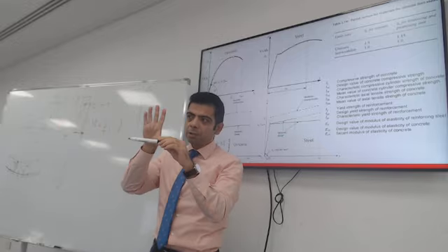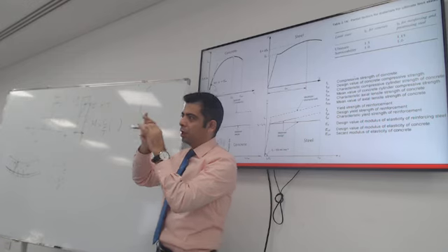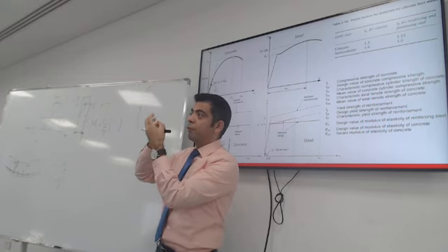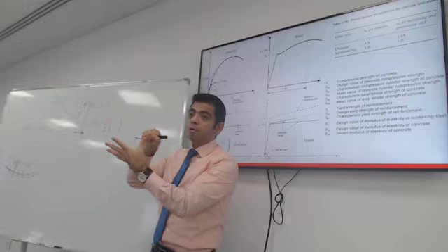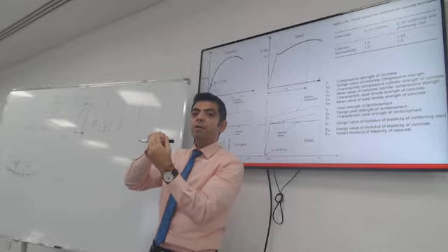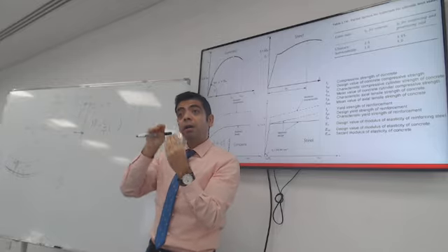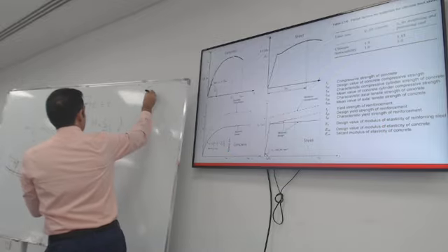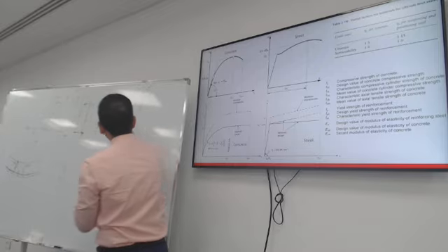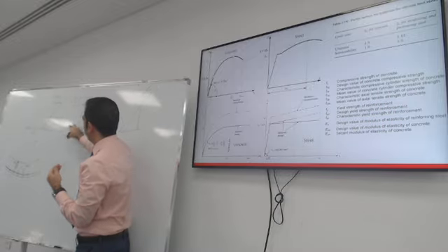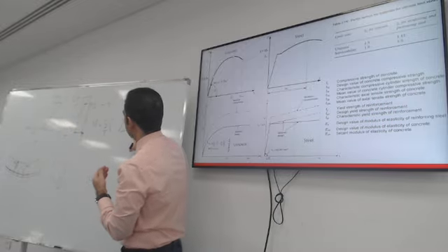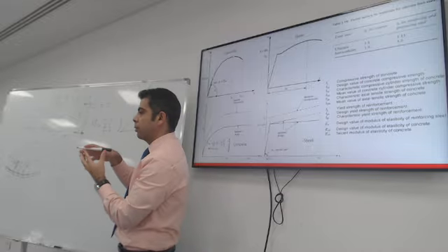Because we assume there is bond between each bar and the concrete, if one moves, the other will move as well. So we will consider that the strain is equally distributed along the section, and therefore we're not going to have this sudden gap that we had in stress. We will assume that the strain in the concrete and steel are going to be equal.